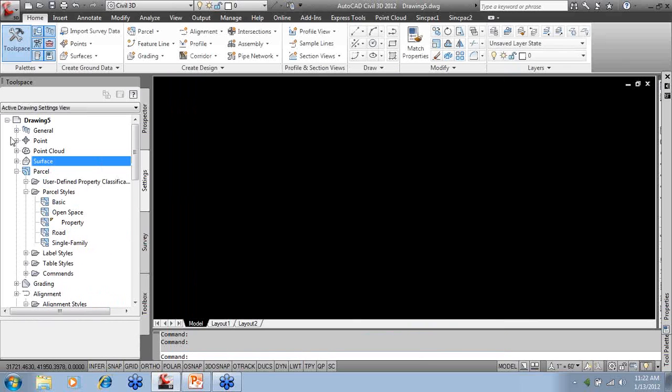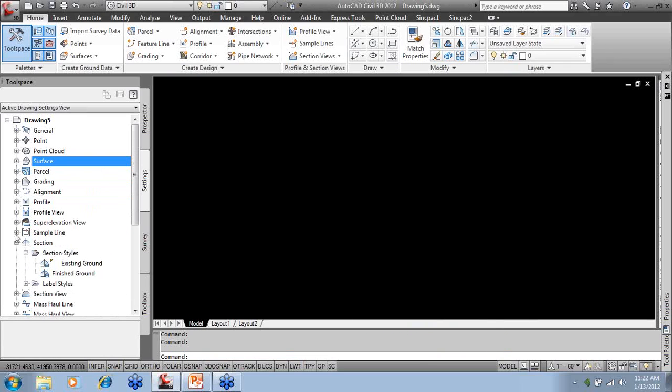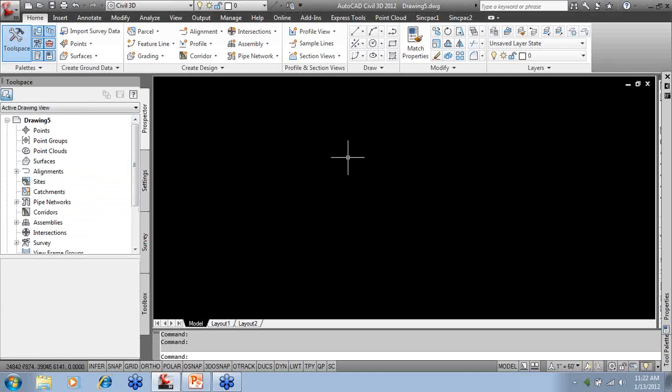So what you were not able to do, if you're in a different version than 2012, you have to do a layer merge. If you go to my blog, there's all the steps to walk you right through it. But what I suggest on 2012 and newer versions, they made it very simple in here. You can just do layer delete. In the past, you couldn't do this because the styles were associated to the layers, and there was no way to separate those. So that's why a lot of companies had difficulty doing that and had to use the ACAD template. So simply go to layer delete.